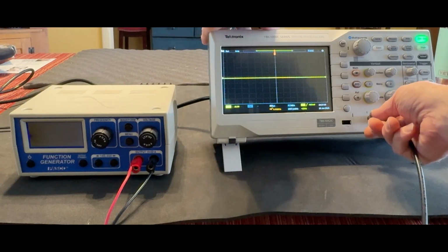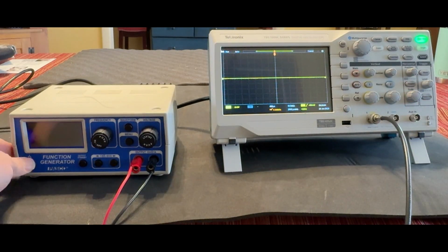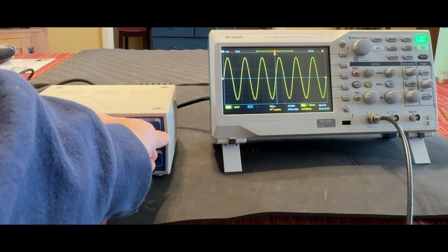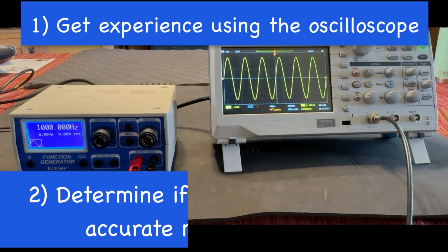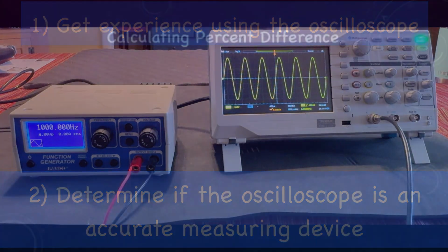In this lab, you're going to hook up a sine wave generator to the oscilloscope and measure the amplitude and period of sine waves with different frequencies. You'll compare the measurements you made on the oscilloscope with measurements you take from the sine wave generator and the voltmeter. The purpose of this lab is to give you experience using the oscilloscope and to determine whether it is an accurate device for measuring amplitude and frequency.